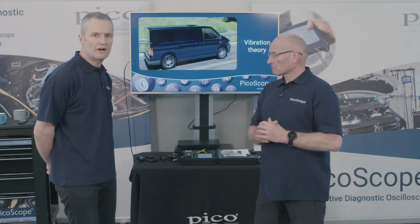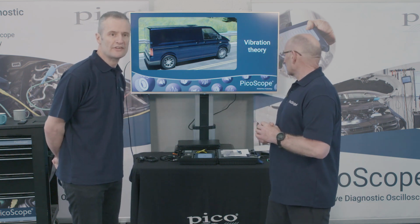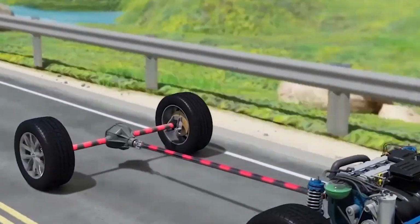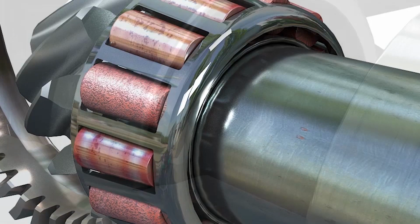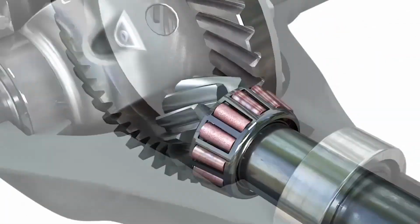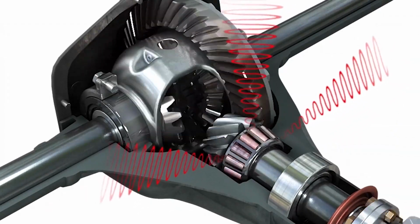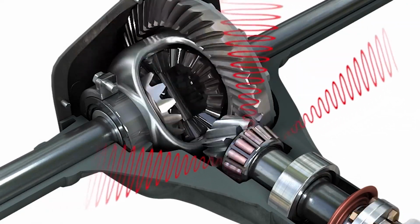Vibration theory, then looking at sound. We talked about vibration being something that we feel, sound now something that we hear. They are one and the same. We experience them differently as humans. The animation here looks at a differential pinion bearing. Look at the condition of this bearing, how it has given, how it's collapsed slightly, and now we have movement in the pinion shaft, and how the pinion gear and the tooth contact between pinion and crown wheel is constantly changing. The noise generated, as you can hear, is horrendous. Of course, as road speed increases, so will the noise level.